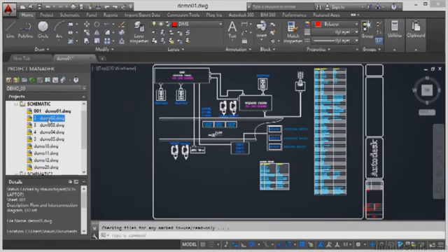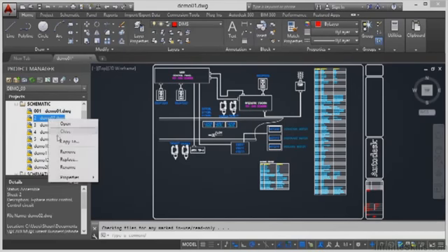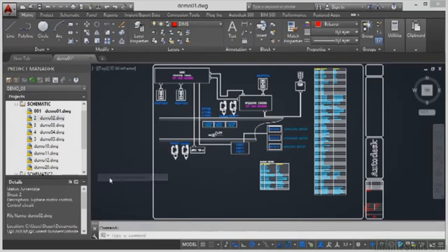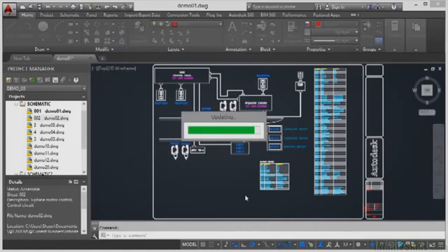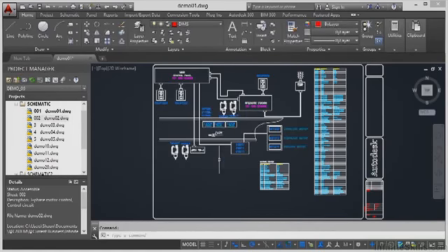So I'll select this drawing now, right click, properties, drawing properties, change the sheet number there to 002, and OK it like so. That'll update. Now that's updating the project. It doesn't update the file name itself. Look, the file name has stayed as demo 02 down here in the details. All you're doing is changing the listing in the drawing list in the project manager.